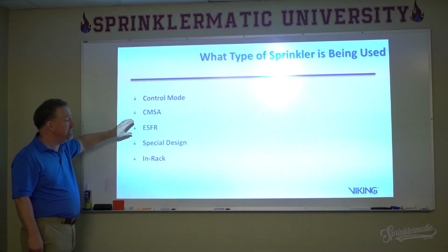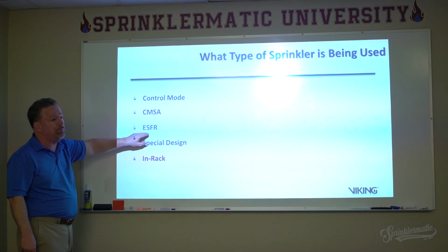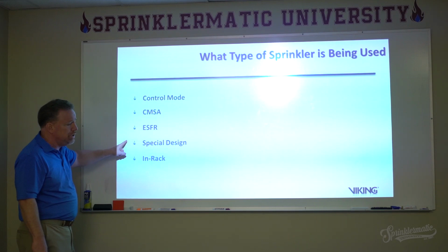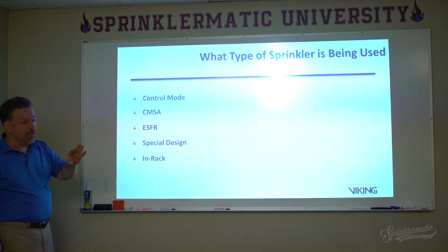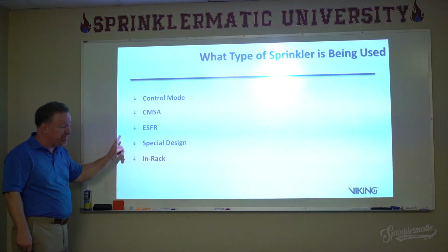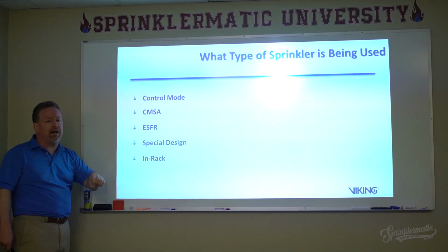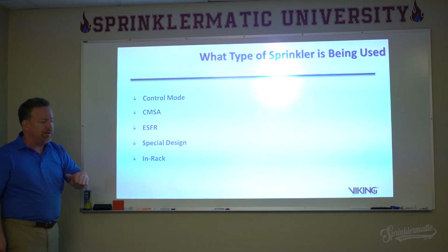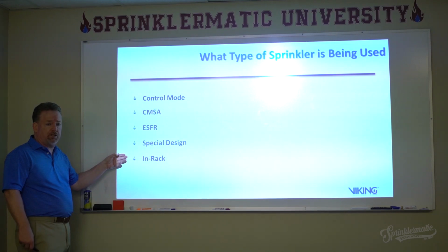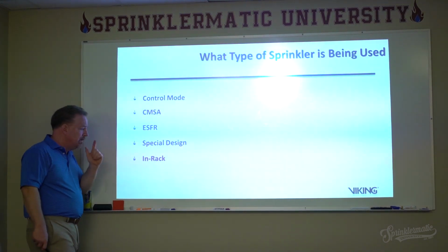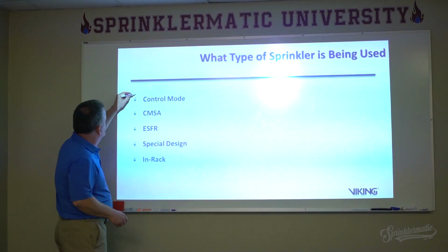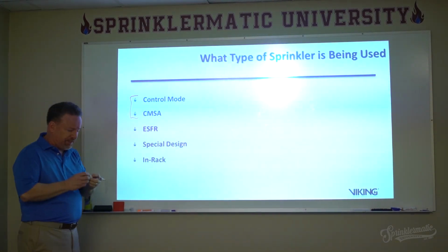Or we're going to use an ESFR sprinkler, which is an early suppression fast response sprinkler. Or are we going to use a special design? Maybe there's a special type of sprinkler or a special design arrangement that is specifically geared towards protecting this commodity in this arrangement. Or do we have to use in-rack sprinklers?